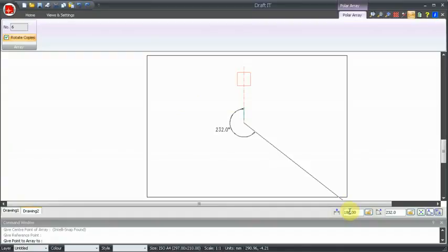Let's just type in a distance to show this. You now see the dynamic line is restricted to 50 long. So it's the angle we need to set. And rather than type it in, we can set it to 60 using the dynamic dimensions and click to accept.